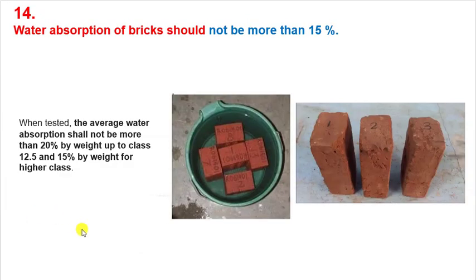And the next and last point for today's discussion is related to water absorption of bricks. A good or higher class brick should not absorb more than 15%. Which brick can we call a high class brick? If that brick is not absorbing water more than 15% by its weight, then you can call it a higher class brick.